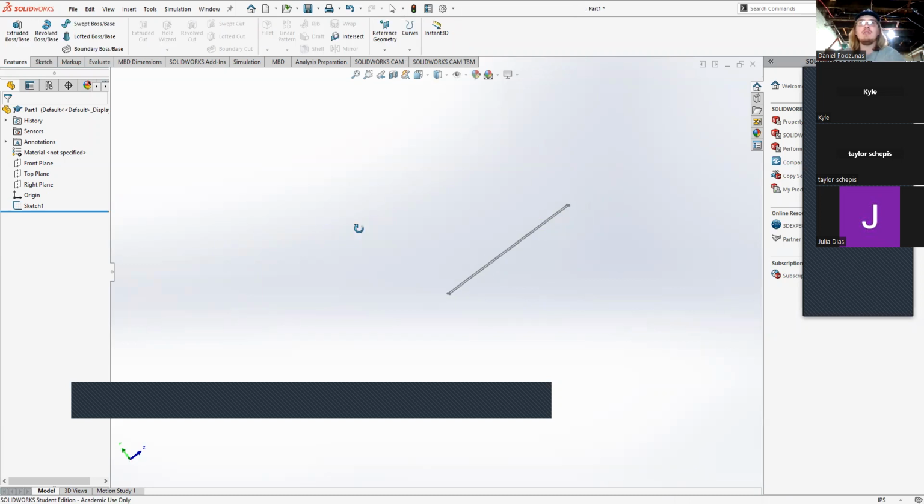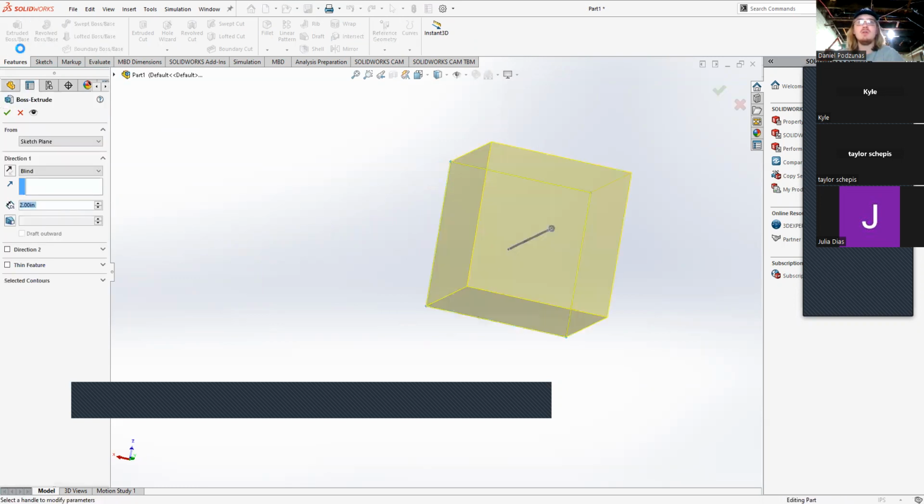And then once you exit your sketch, this thing down here is called your feature tree, where you have your list of just a bunch of stuff. And we have our sketch 1. That's the sketch we just made. I know Fusion has something similar, but it looks a little different. But if we click sketch 1 and then click features, we can do the same thing. So you can basically choose to do your extrudes while you're still in your sketch, or you can wait, close out your sketch, and then do the extrudes. It does the same thing.